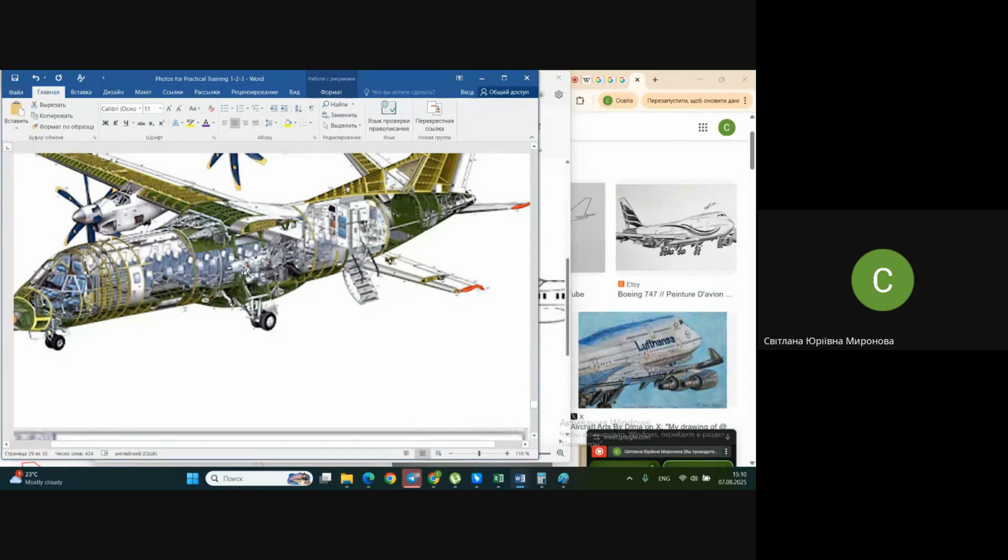So mid-wing, with closing the loads to the frames, is possible, yes, but in this case it will be overweight in comparison to another design decision of inner structures, even than low wing or high wing. Once again, for passenger airplane, higher wing maybe is not a good decision, especially if you use engines below the wing, let's say, in front of the passenger cabin at some distance.